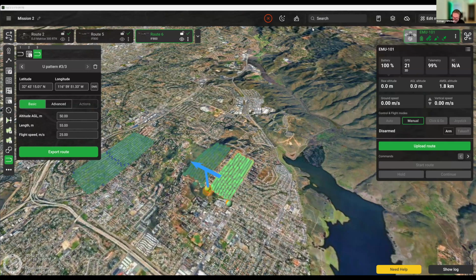Then the next question is, does this also work for a DJI Air 3S? So, yeah, the Air 3S is more of a consumer grade drone, and unfortunately you can't really do LiDAR surveys with it. And also, since it's not really supported in DJI MSDK, we also can't support this drone fully. But I know that for many of these smaller DJI drones, you can still do photogrammetry missions with them, but it can be a bit more tricky. There are some that are supported in DJI's SDK, such as the Mini 4 Pro, which we also support, and for this you can do the flights directly.